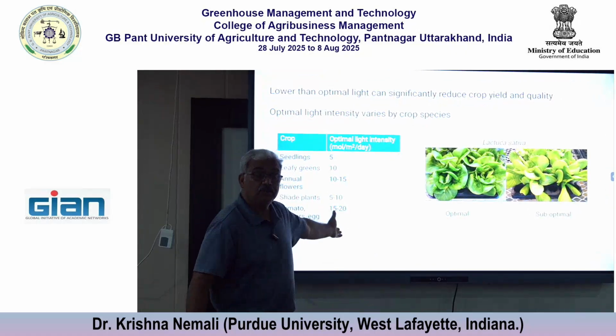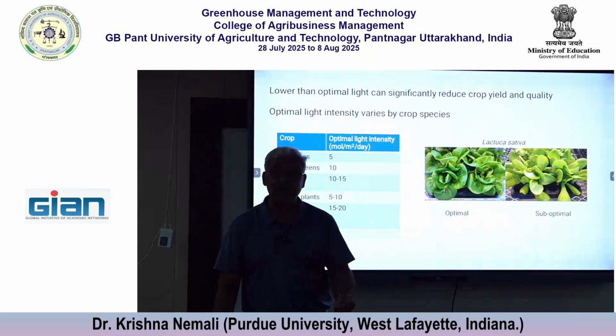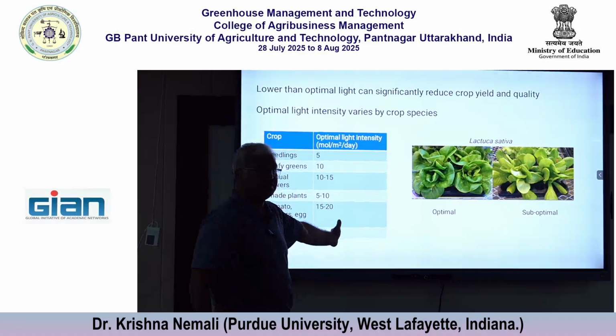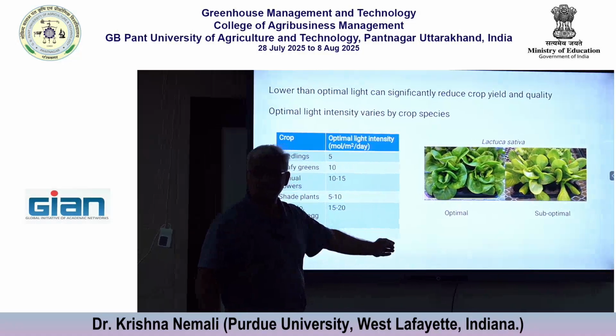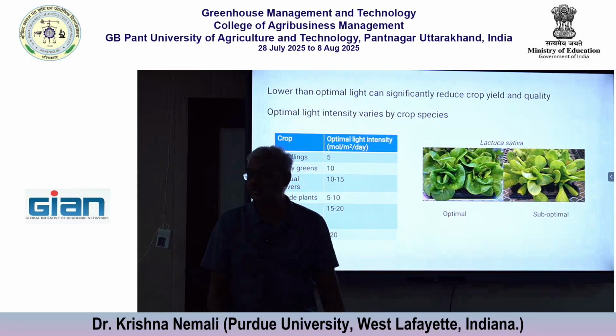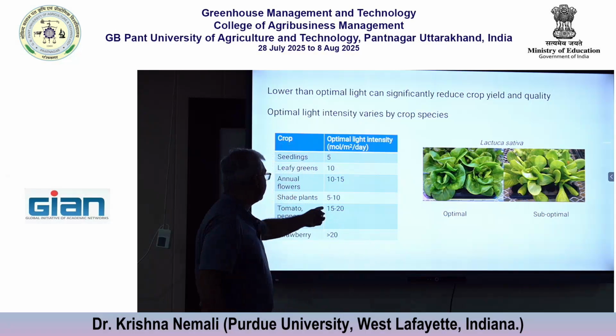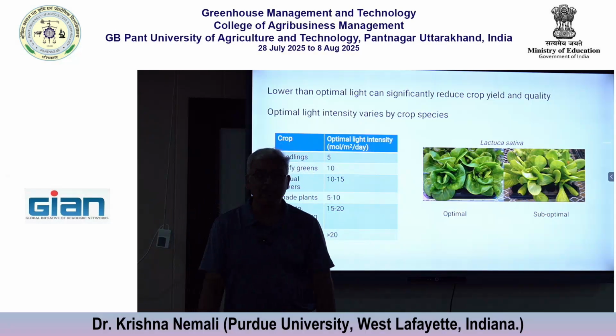Okay. Now, that number is something you can use as a guideline, right? You need a sensor to know how much light you are getting. Without the sensor, these numbers mean nothing. So the important thing is you have to invest in a light sensor if you have a greenhouse. There is no escape from that. You may at least have one good light sensor in the middle of the greenhouse. If you can't connect it to a data logger and continuously monitor the numbers, at least have a handheld unit and periodically measure the intensity. And if the intensity values are lower than that, you may have to turn on artificial lights. Otherwise, you won't get quality. Otherwise, you won't get the yields that are desirable.